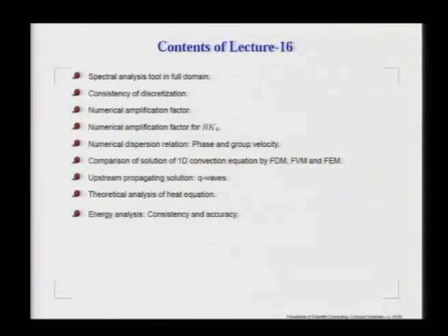Once we apply it to a specific space time dependent equation, we can talk about numerical amplification factor. We have seen already that Euler time discretization with various kinds of central schemes are unstable, and that is why we would move over to numerical amplification factor for the 4-stage Runge-Kutta method, because we have already talked about the requirement of single step method as opposed to multi-step methods.